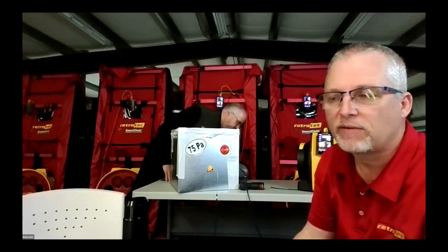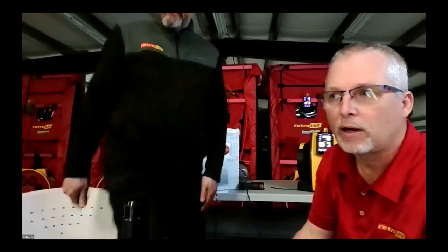you can hook multiple units up in parallel, and that gives you the opportunity to test larger systems. I recently talked with a customer testing a very large air handler, and they had 10 units hooked up in parallel, which gives them about 3,000 CFM of flow. Others have used 2 or 3, but putting them in series, one blowing into the next, does not help you. You need to hook them up in parallel.